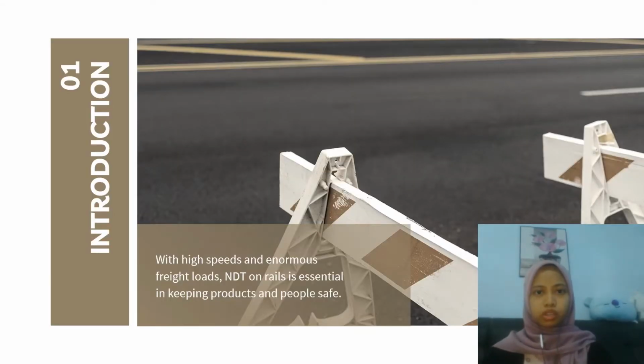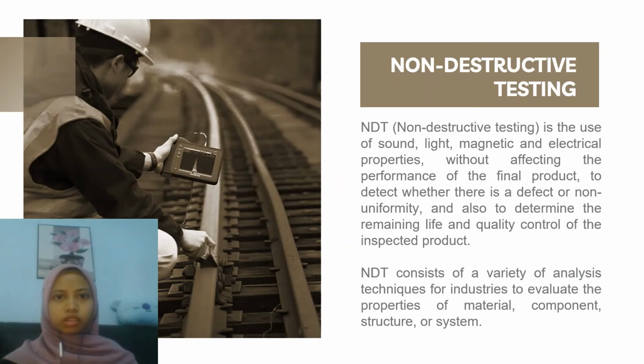Introduction. With high speeds and enormous freight loads, testing on wheels is essential in keeping products and people safe. Non-destructive testing is the use of sound, light, magnetic, and electrical properties without affecting the performance of the final product to detect whether there is a defect or non-uniformity, and also to determine the remaining life and quality control